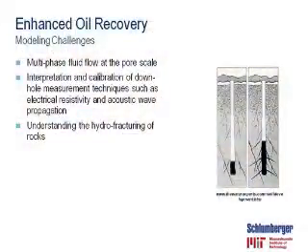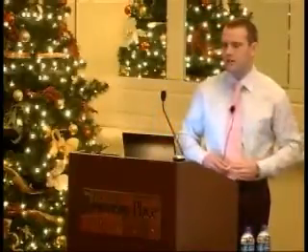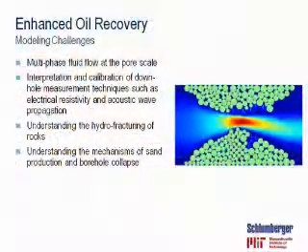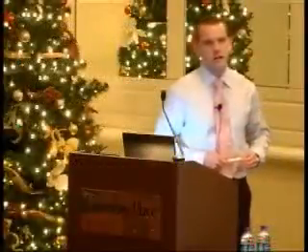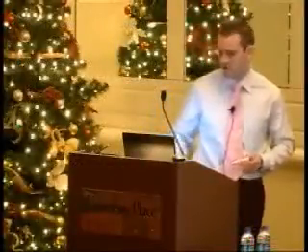Hydrofracking is a technique that's been used to some success and increasingly thought of as a decent method to increase the permeability of rock. So high pressure water will fracture the rock, hopefully increasing the permeability and the flow rate of the oil, but being able to work out the best way to do that and whether it's actually going to have an advantageous effect is very important. Sand production and borehole collapse: moving fluids will erode the media through which they're flowing and may change the actual permeability of the rocks.